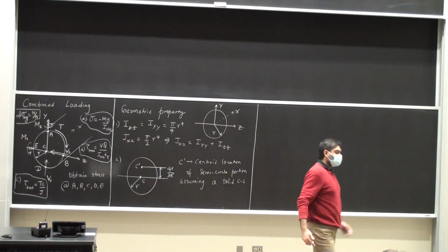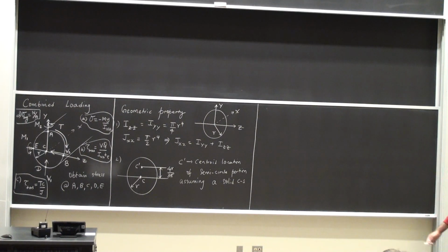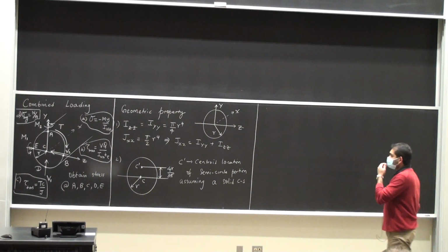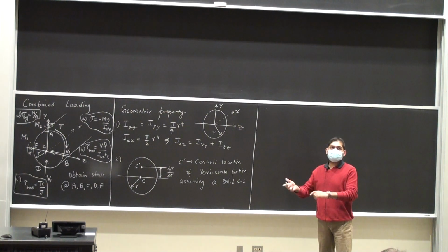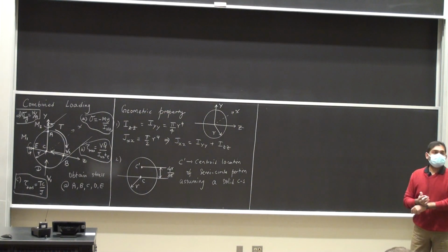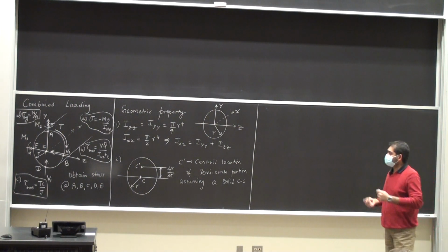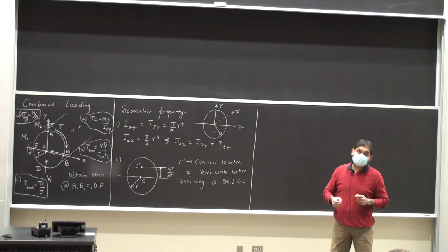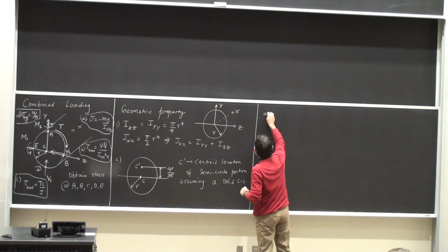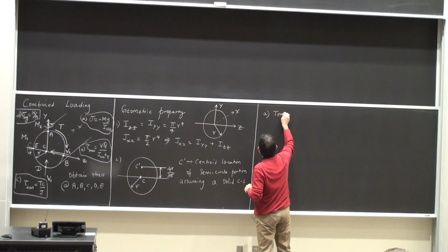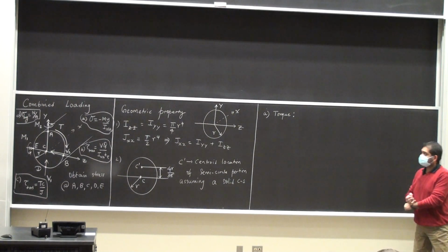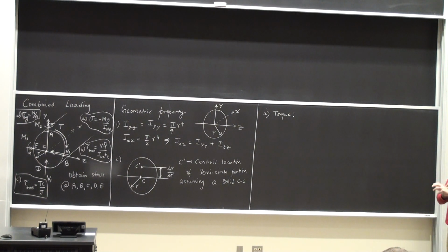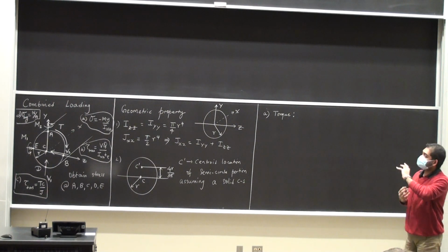So in this problem you have to be very methodical. Okay, this is the only saving grace in all these problems. You'll have to start looking at the effect of each and every one of them and then figure out, okay, what are the stresses due to these things. Okay, so let me start looking at the effect of the torque first. It's the easiest of the lot because we know the direction of the shear stress due to the torque applied at each and every point.